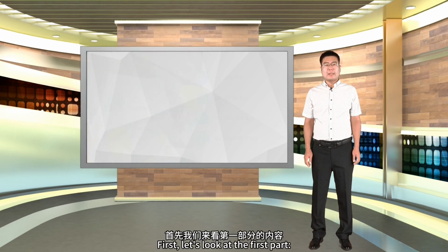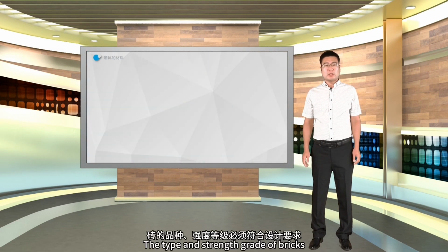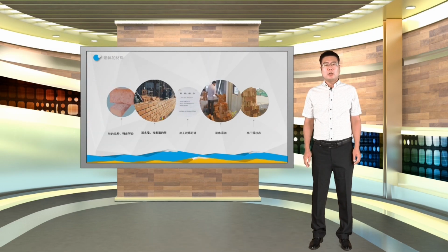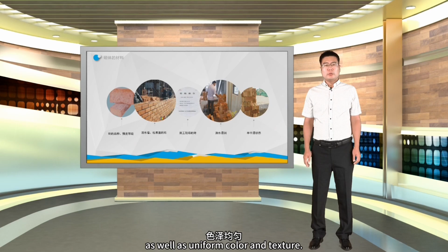First, let's look at the first part, preparation of bricks. The type and strength grade of bricks must meet the design requirements, and their dimensions should be uniform. For exposed brick walls and columns, the bricks should also have neat edges and corners, as well as uniform color and texture. Bricks delivered to the construction site must be retested in a lab, with a retest report provided.